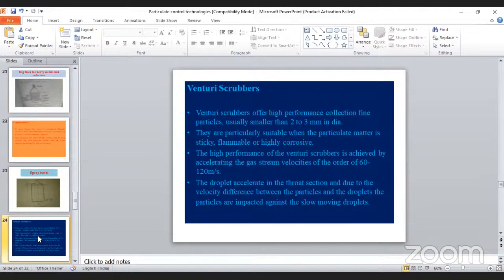But in the cooling spray tower, suppose some hydrocarbons are there. All the hydrocarbons cannot be condensed at room temperature. And some of the hydrocarbons are highly volatile at room temperature. They may not be settled and they may stay along with the gas stream. Then if it reacts with the water, there is a possibility that some of the alkanes can be converted into alcohol. And many other things are there. Any oxides that are there will be converted into their respective hydroxides.